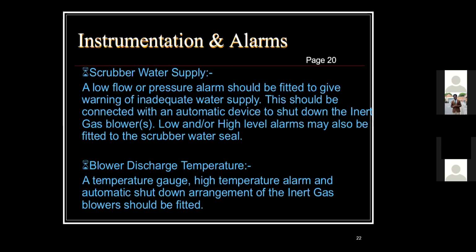Sometimes the alarms can be low or they can be high. As the common saying goes, too much of everything is bad. So when you have a high water level, it's also going to trigger an alarm and it shows that something is wrong. So you need to understand and check. You need to check the discharge valve, how it's being monitored. You have to reduce it because it's a ballast line system you're using.